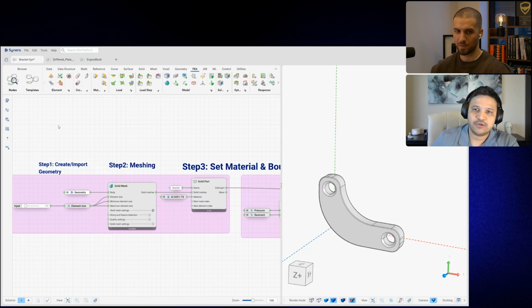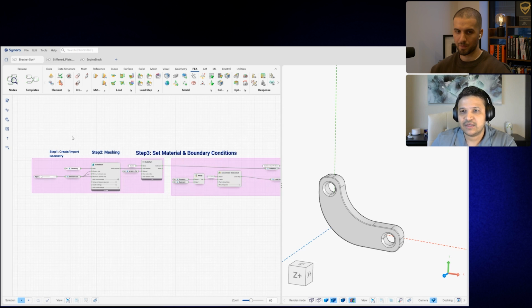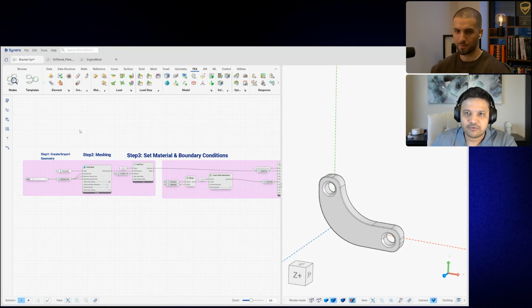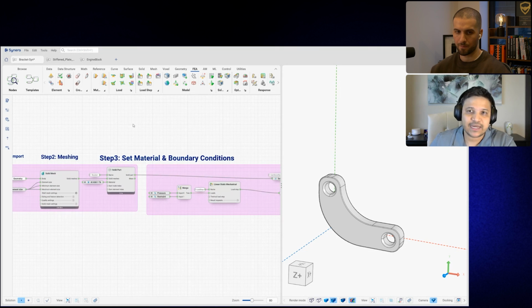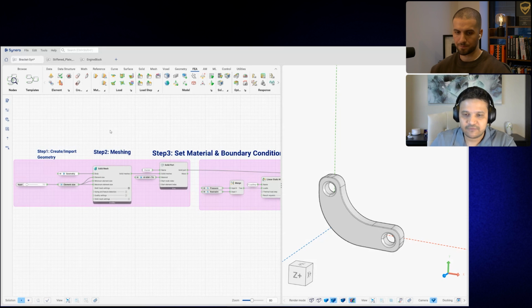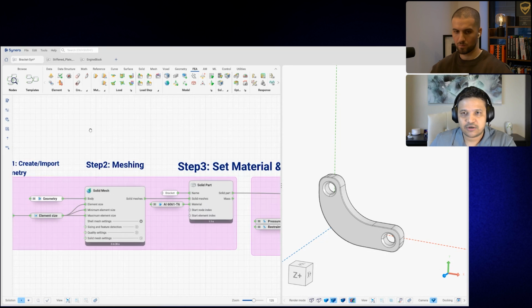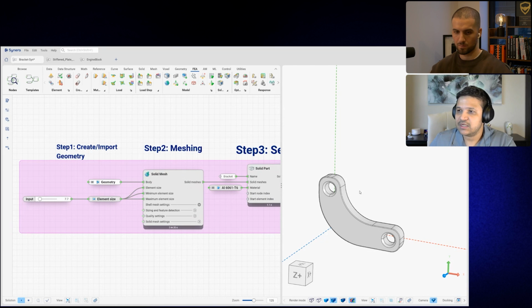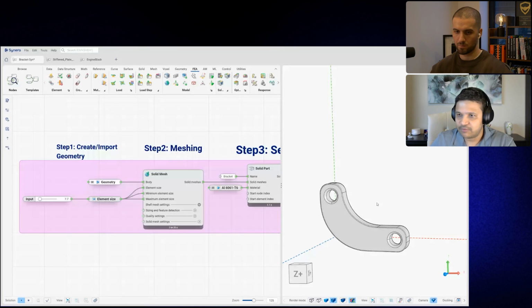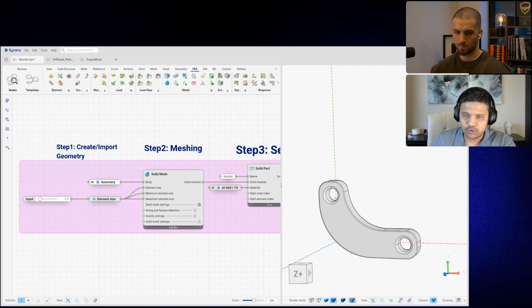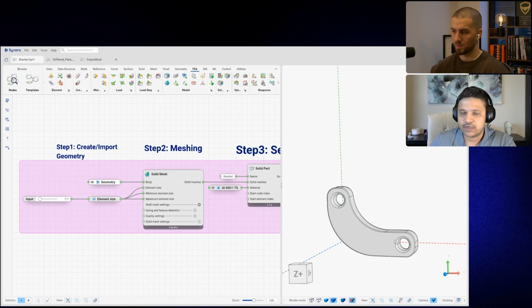Today, what I'm going to do is walk you through a basic traditional FE, what you go through. You already know, but I just want to recapture that and show you where Intact comes in and how we can help accelerate the simulation process for you. So let's just start up. First of all, there's a very simple part, a basic bracket where we're going to fix one hole and then put the load on the other hole and then run an analysis on it.